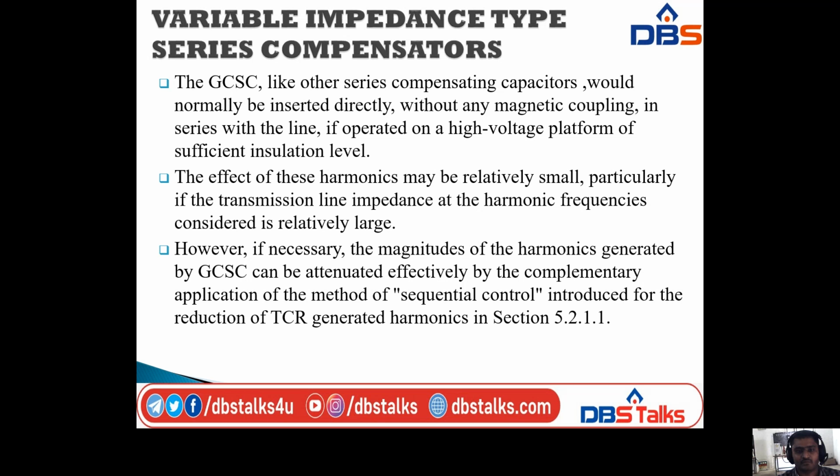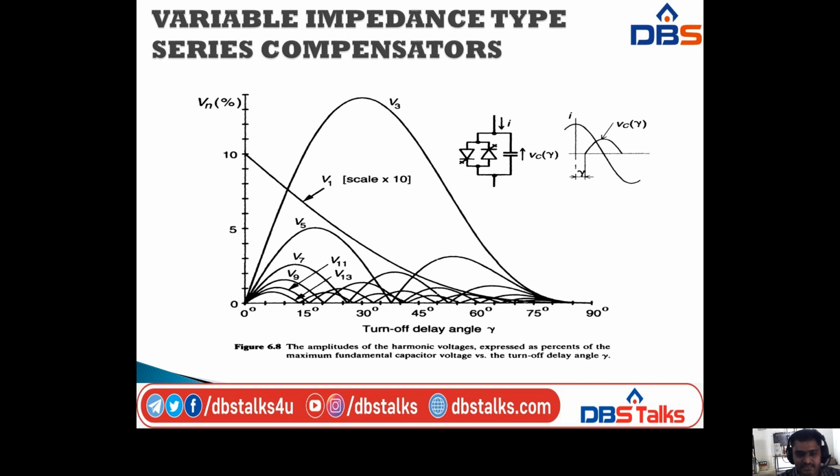So this is the diagrammatic representation of the explanation. Here I am taking Vn, that is the voltage, against the turn-off delay angle gamma. Here gamma is taken between 0 degrees and 90 degrees, and we have different curves for V7, V9, V11, and V13, all of them odd harmonics.